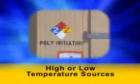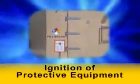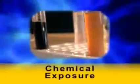Look for high or low temperature sources that could result in burns, eye injury, ignition of protective equipment, heat-cold stress, or frostbite. Sources of chemical exposure. Sources of hazardous dust or particulates. Sources of light radiation, such as from welding, brazing, cutting, heat treating, lasers, metal halide lamps.